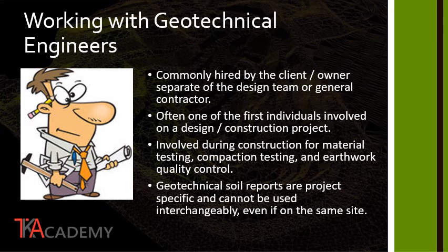Although a soils report is generated early on in a project schedule, the geotechnical engineer is typically involved during construction for material testing, compaction testing, and earthwork quality control. One final thing to keep in mind is that the geotechnical soil reports are project specific and they should not be used interchangeably even if the project is on the same site.